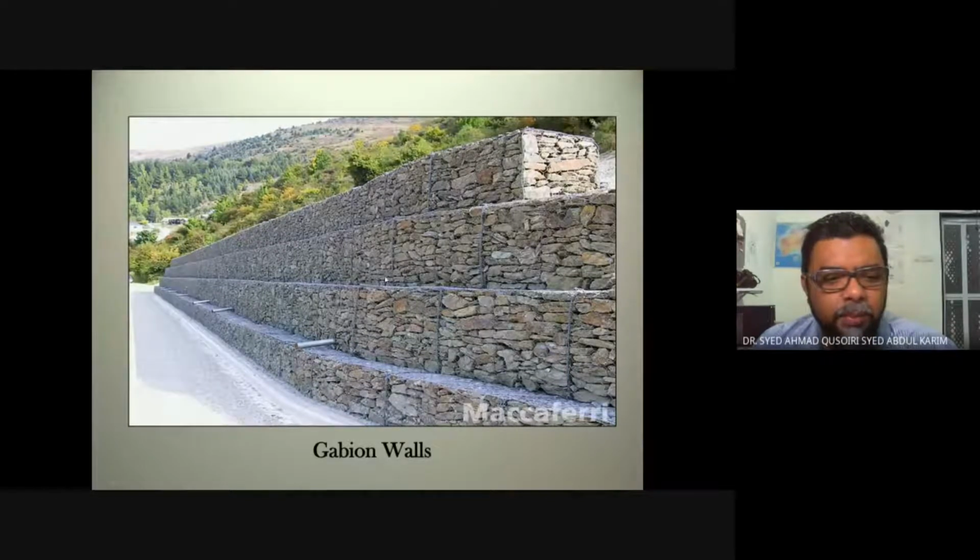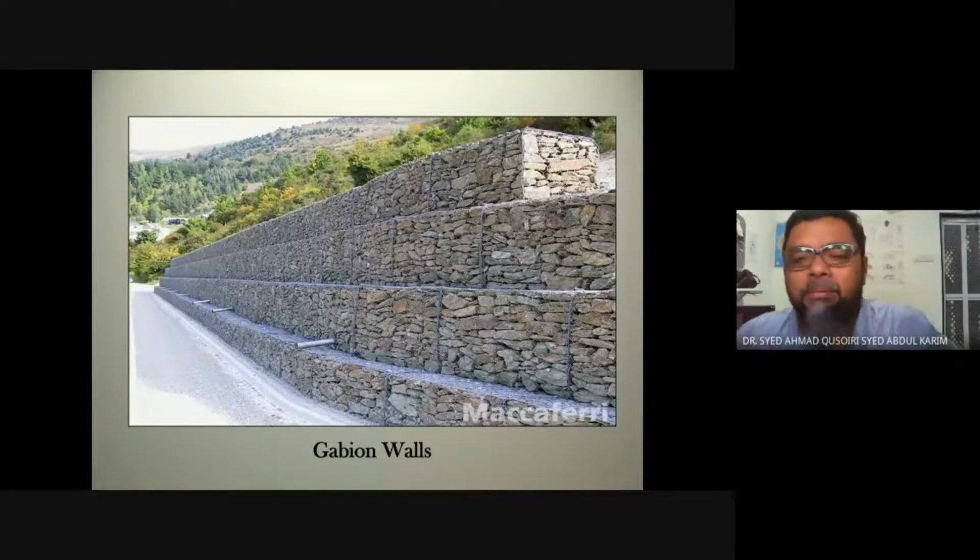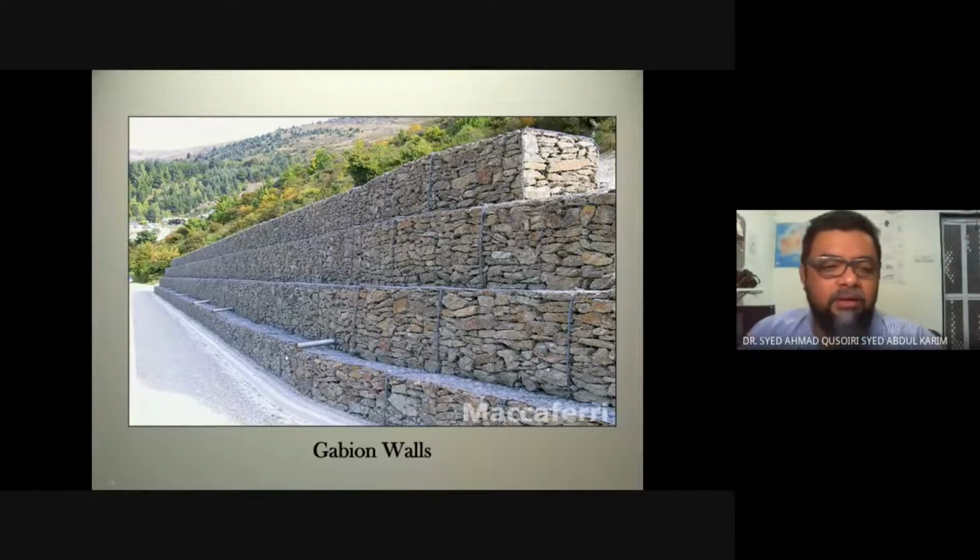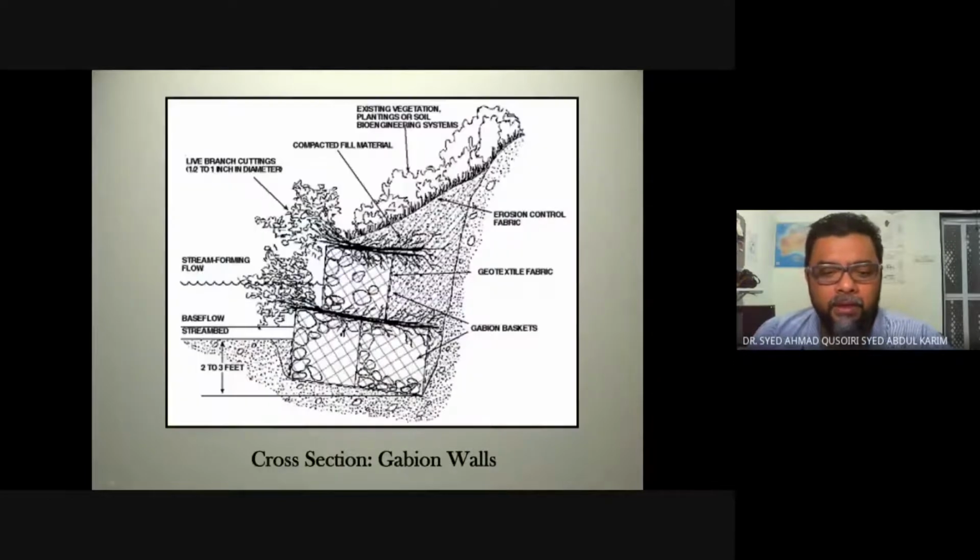And they even prepare a weep hole, okay, to further speed up the process of water being ejected from behind the gabion walls. So it doesn't really need it, but to speed it up, we can have these weep holes installed. Okay, so an example of a gabion wall.